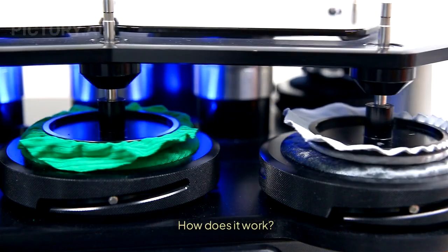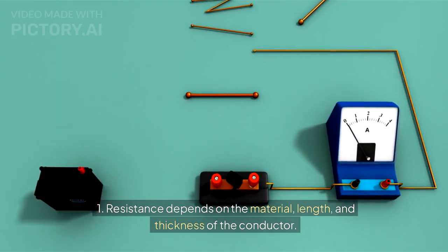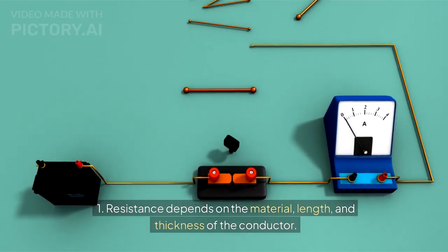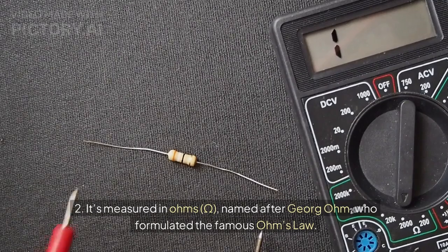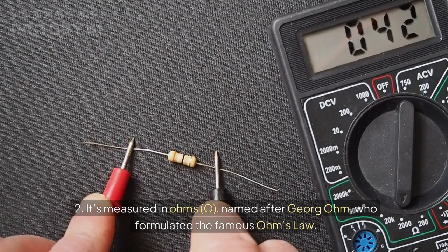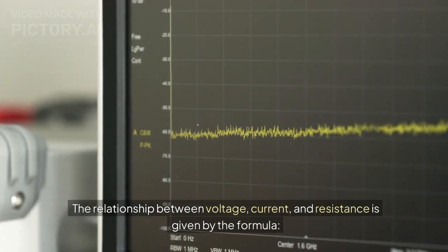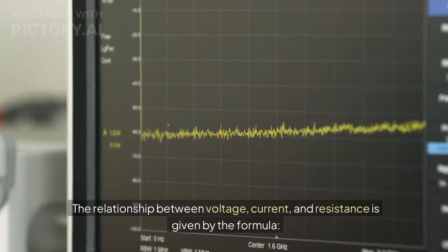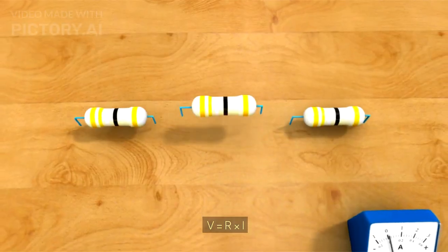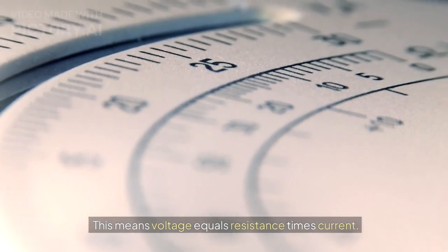How does it work? 1. Resistance depends on the material, length, and thickness of the conductor. 2. It's measured in ohms, omega, named after Georg Ohm, who formulated the famous Ohm's law. Ohm's law. The relationship between voltage, current, and resistance is given by the formula V equals R times I. This means voltage equals resistance times current.